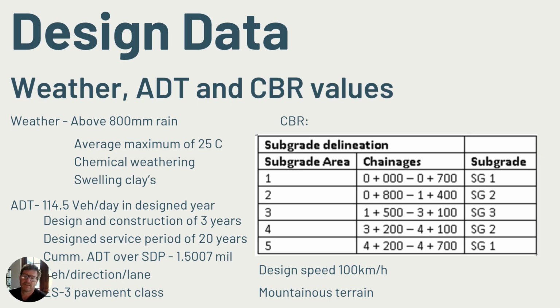The delineated subgrades along the center line are presented in the table on screen, with the design subgrade for the required changes. The subgrades vary from subgrade 1 to subgrade 3 depending on the value of the lower 10th percentile obtained from the specific area.